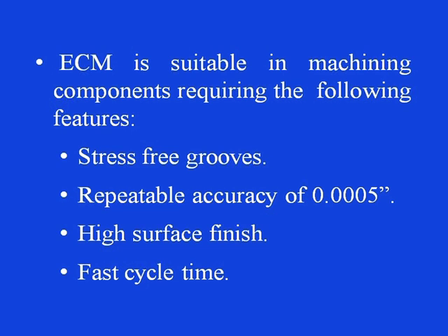ECM is suitable for machining components requiring the following features, like stress free grooves, as there is no mechanical machining phenomenon involved in this process. Therefore, mechanical stresses are not developed. Then repeatable accuracy, something to the tune of 0.005 inches. Then parts where very high surface finish is required, at the submicron level, and where fast cycle time is a requirement.